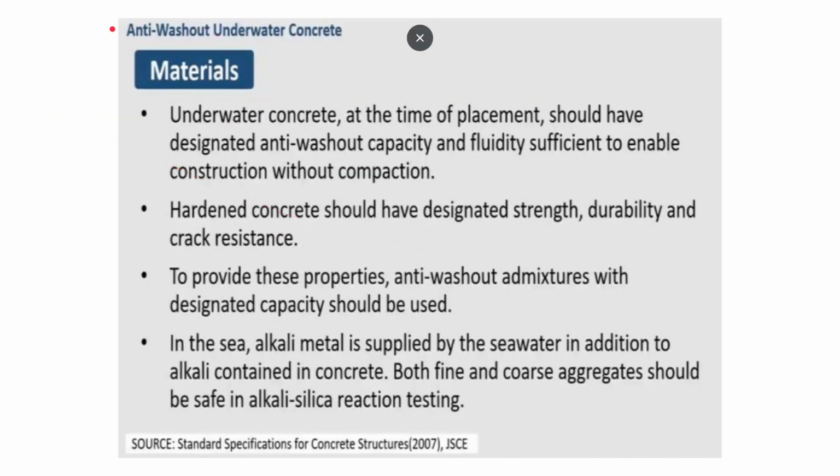Okay, now let us go through anti-washout concrete. Okay, so this is an underwater concrete. At the time of placement it should have designated anti-washout capacity using the viscosity agents and fluidity sufficient to enable construction without compaction. Hardened concrete should have designated strength, durability and crack resistance. For providing these properties, anti-washout admixtures with designated capacity should be used.